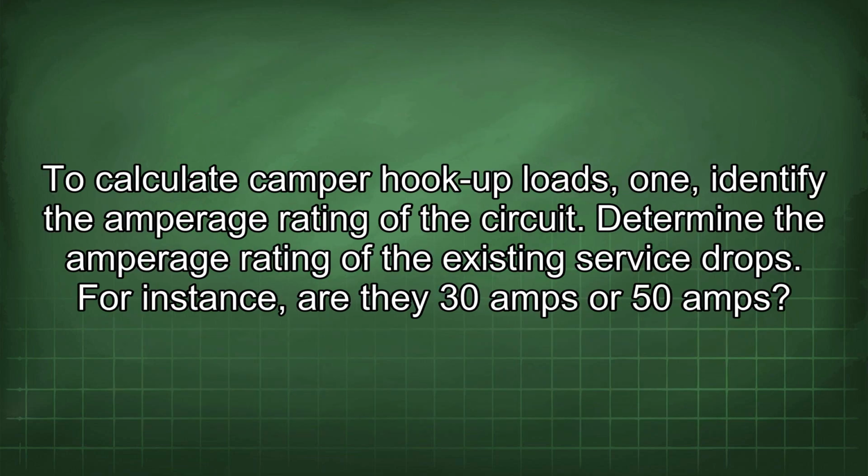To calculate camper hookup loads, 1. Identify the amperage rating of the circuit. Determine the amperage rating of the existing service drops. For instance, are they 30 amps or 50 amps?